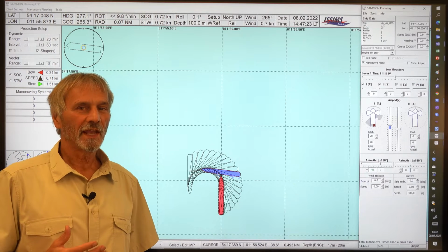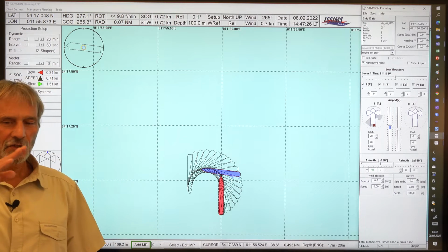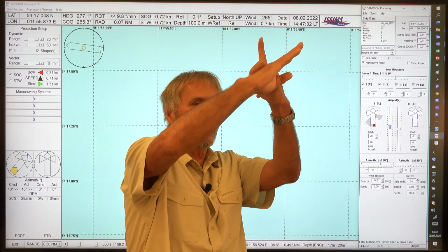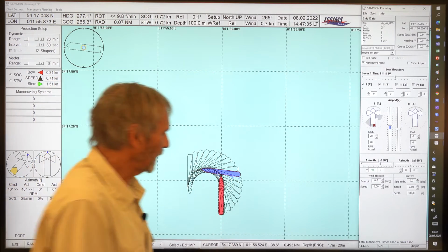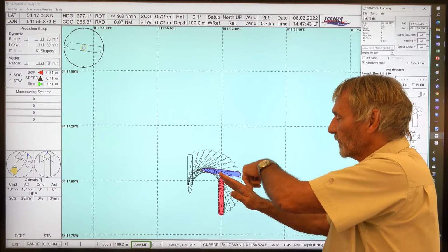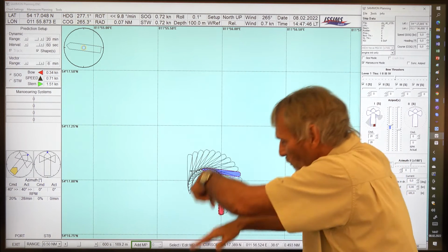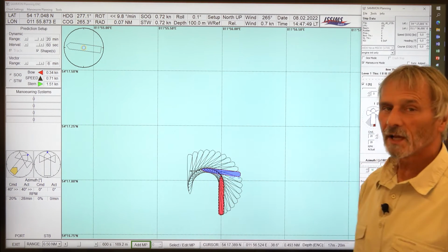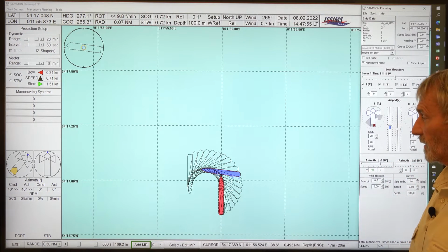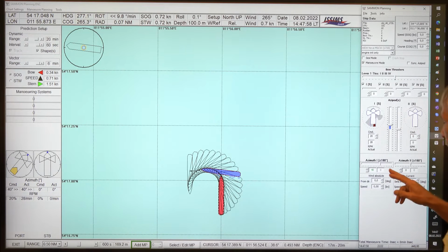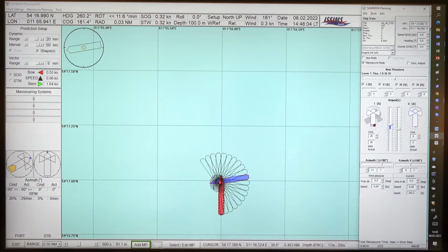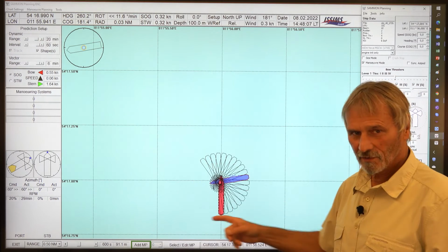Lift comes from the aeroplane dynamics. So if a wing is going like this, and then we have a lift force heaving the plane up. We have now here the ship in the vertical plane. So if we have a lift force from here, then the ship is pushed into this side. So this motion comes from the effect of the drift angle. And you see the drift angle is very big here. Okay, when we blow it up further to 60 degree, now maybe here, so we see the ship makes not a turning circle anymore.